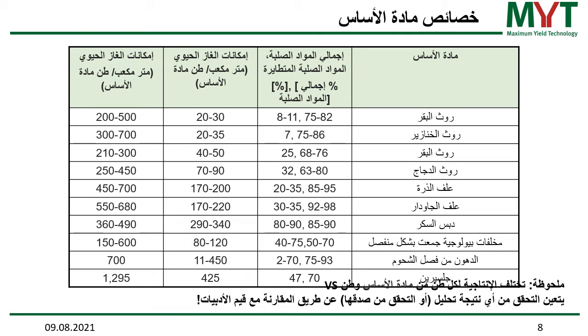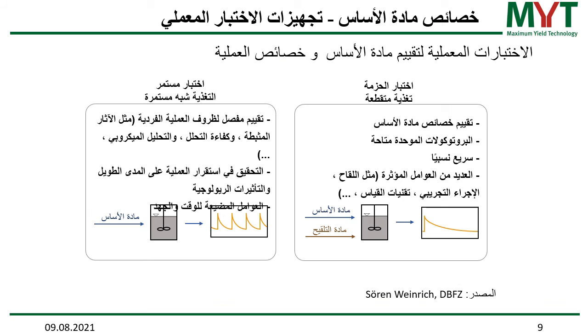Then there are two examples at the very bottom: lipids from a grease separator, or glycerine, which is a byproduct from biodiesel production. Such industrial wastes can be very valuable co-substrates for your overall process, because they contain a lot of gas potential.